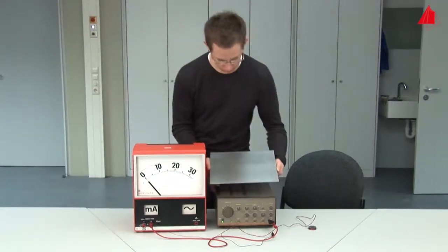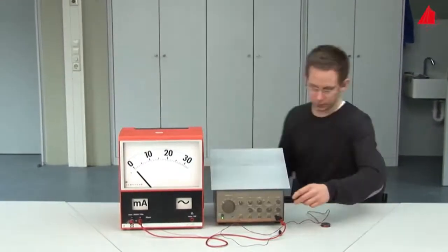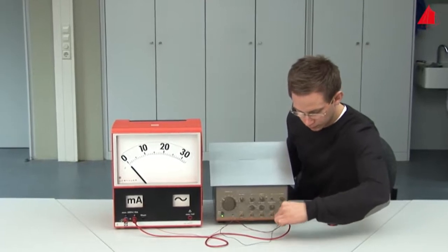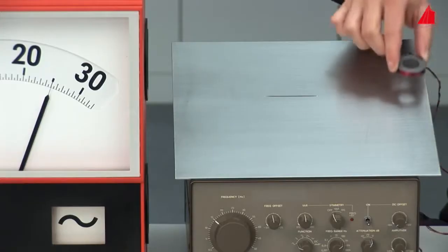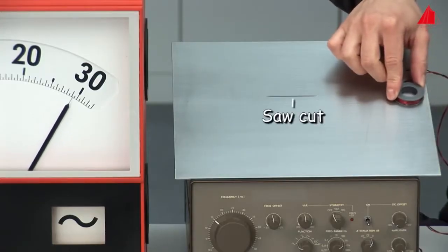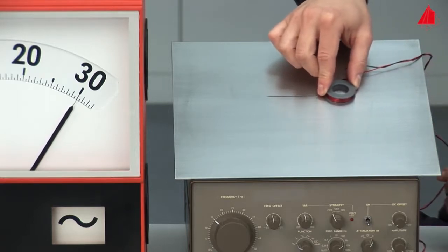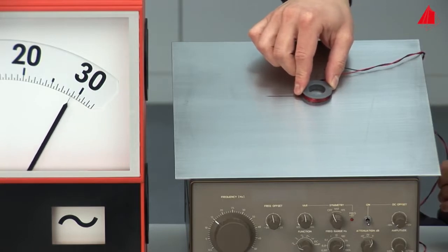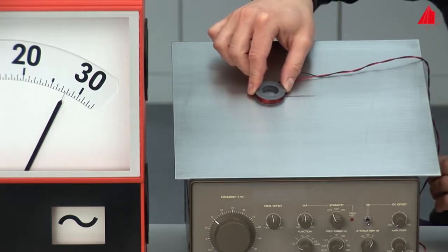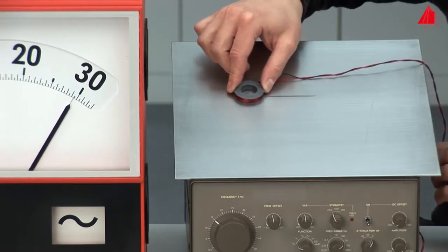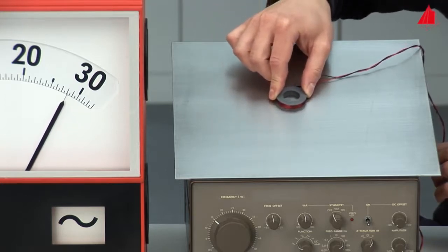Here the test piece is not a tube, but a sheet, again made of an austenitic steel. It has a saw cut in the middle, going right through the sheet. In contrast to the coaxial probes, the coil is not pushed over a tube, but instead placed with its flat side on the surface of the test piece. In defect-free areas, the current consumption of the coil is high. In the area of the saw cut, the current drops noticeably and reaches its full height again in the intact area. The same effect can be observed when the coil is moved across the saw cut from top to bottom.